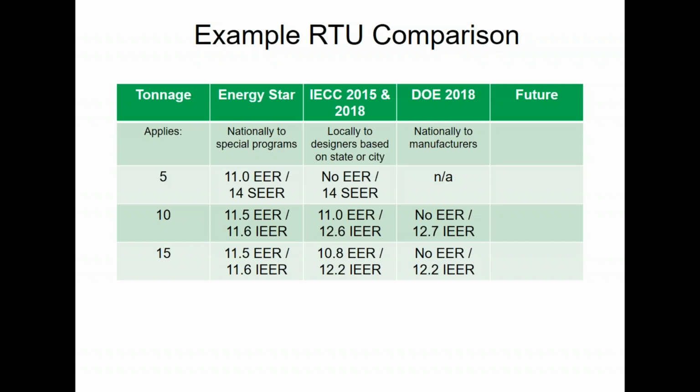If I look at the 2015 code as compared to the 2018 code, there are going to be no changes. So in Illinois, when we go live with the 2018 IECC next March, it will not affect your rooftop efficiency. It'll affect other stuff with the rooftop, but not the EER and IEER efficiency.